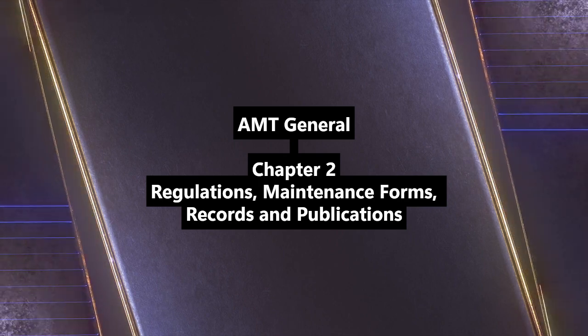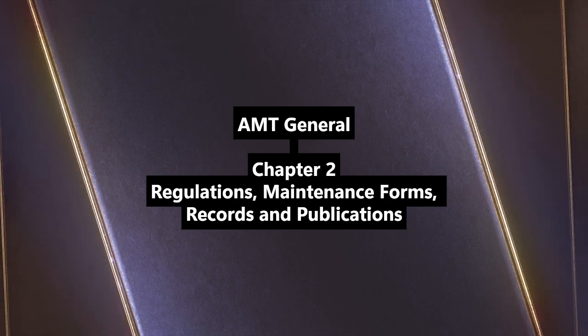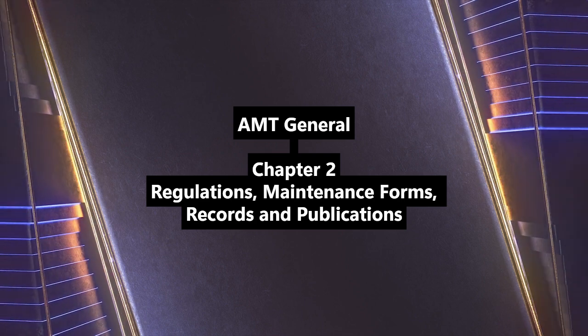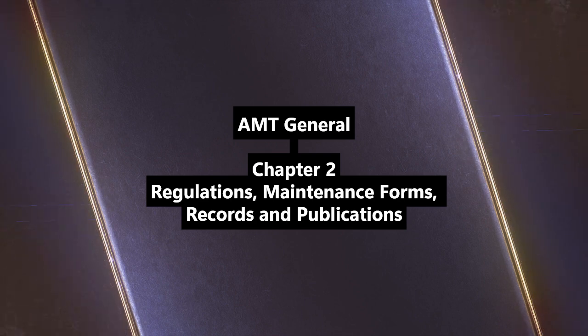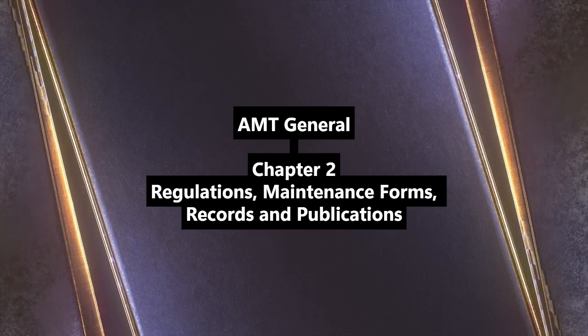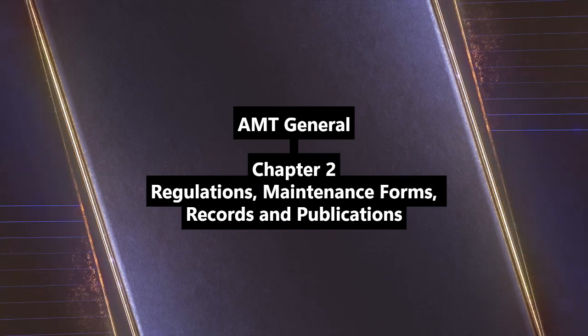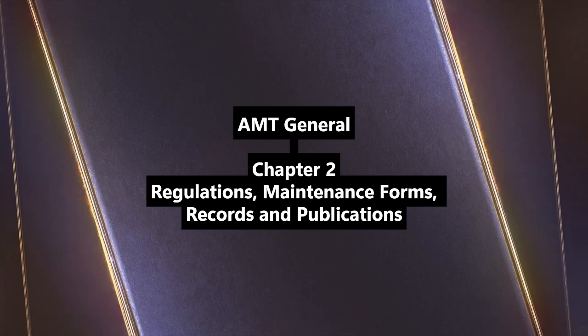Paragraph A2 covers permanent records kept as long as you operate the aircraft and transfer it upon sale. What's included in permanent records? Total time, airframe, engine, prop, life-limited part status, time since overhaul for required items, current inspection status, current AD status, and Form 337s for major alterations.